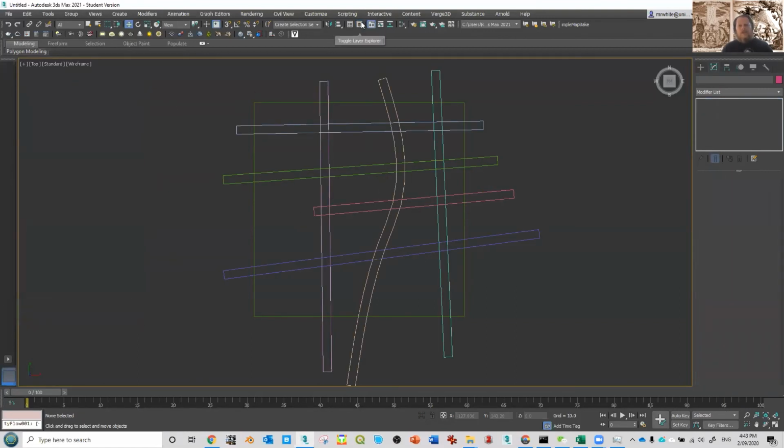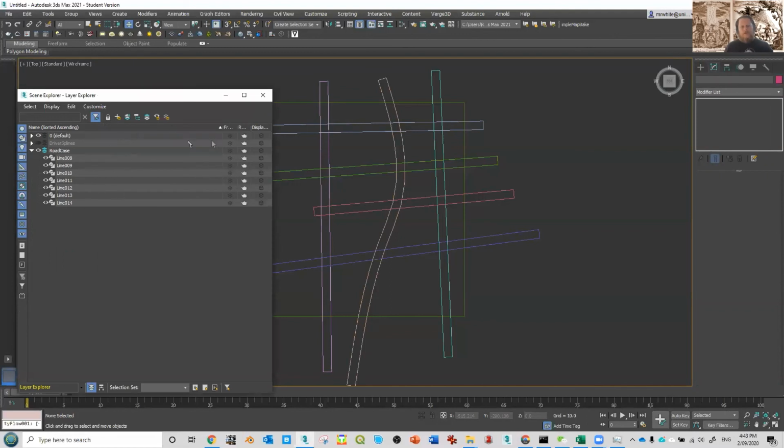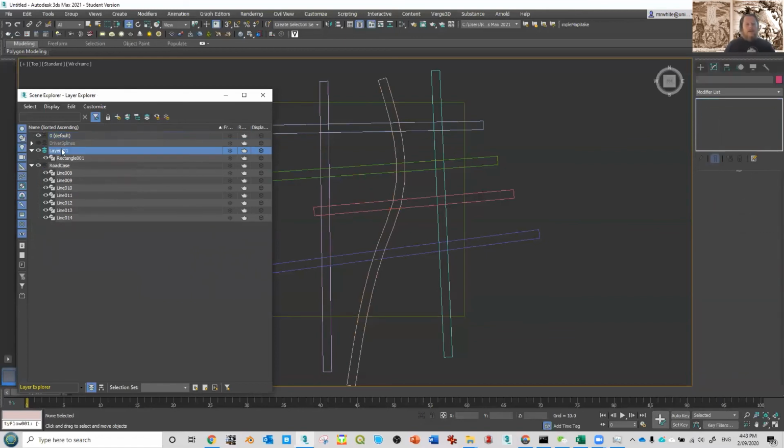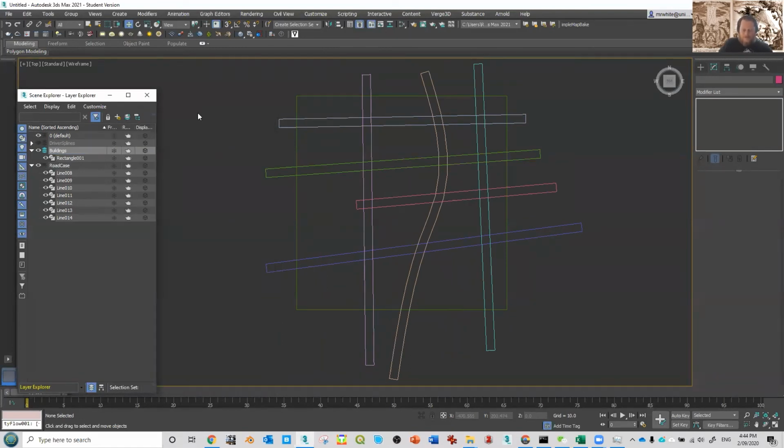So if you bring up the layer dialog through this guy, sometimes it's set to be on this guy, which is hierarchy, which sort of lists everything, and you just need to click on this guy next to it. Okay. And then anything you've got, you can make selections and sub-selections. So if I grab this guy and made a new layer, it'll plonk that onto the new layer, and you click a second time and it'll let you change the layer. So I'm going to call this geometry buildings. Okay. Any other questions on any of that?